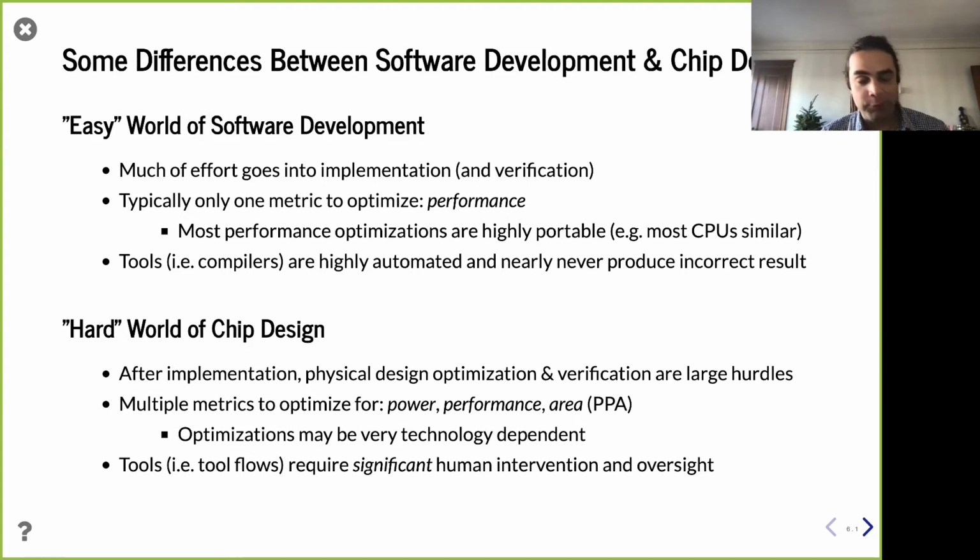And so when we're doing hardware design, simply getting it working or just getting it implemented, that's the starting point, right? Actually making it work well in physical hardware as well as verifying are large hurdles, right? And the reason why is when you write code for a processor, the compiler, compiling down to assembly, that general machine code, is pretty good at that. There are optimizations that are pretty good at that. When it comes to mapping your RTL to a physical implementation technology, there are some things that CAD tools can do extremely well. And occasionally, and sometimes unpredictably, they do a poor job, right? And so kind of looking over the shoulder of these tools and seeing what they are handling well, what they are having trouble with.